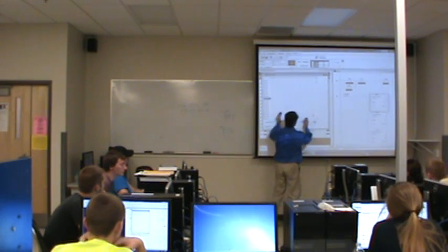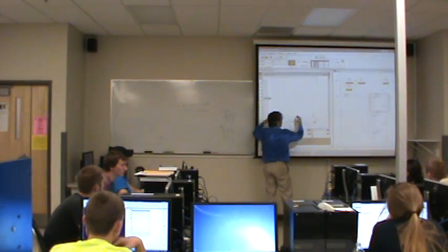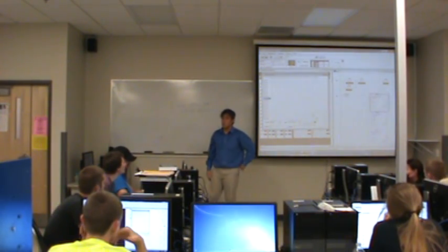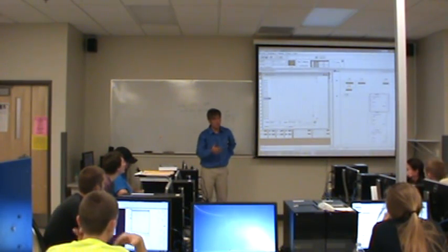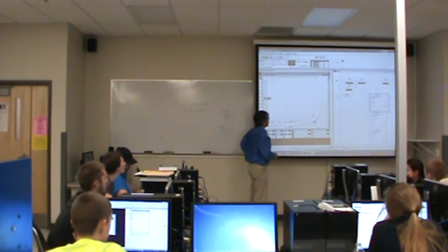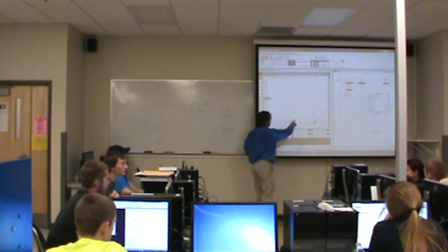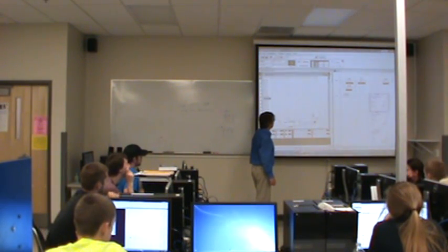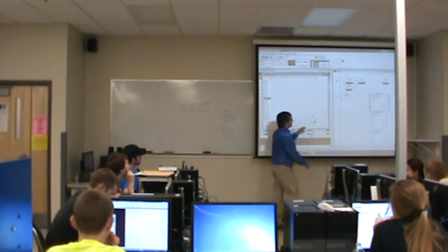Why do I want to do that? Well, that leaves these other bits available if I want to use them. A lot of times you end up running out of memory in your programs because you have so many things that you need to remember or that you need to put in memory. So this is just a way where I can salvage these other bits and reuse them if I want to.